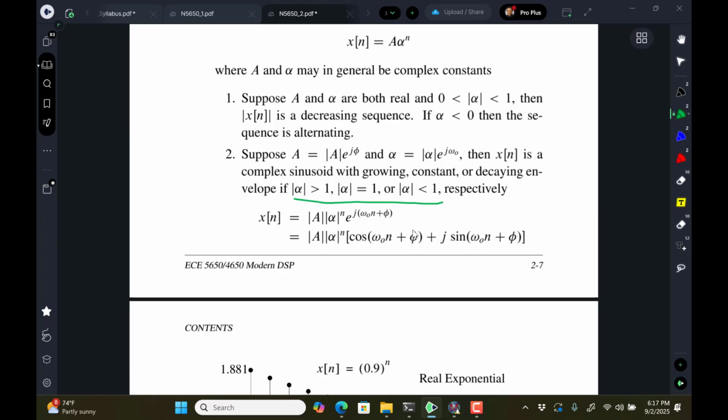So with that, we can create this form, which is probably our most preferred form in digital signal processing, because we generally think of complex exponentials or sinusoids as being a valid signal. I realize in the lab you don't think of it that way because you only think of a sine or a cosine, but in a communication signal scenario that we deal with in DSP, a complex sinusoid is very, very real. It happens all the time, as a matter of fact.